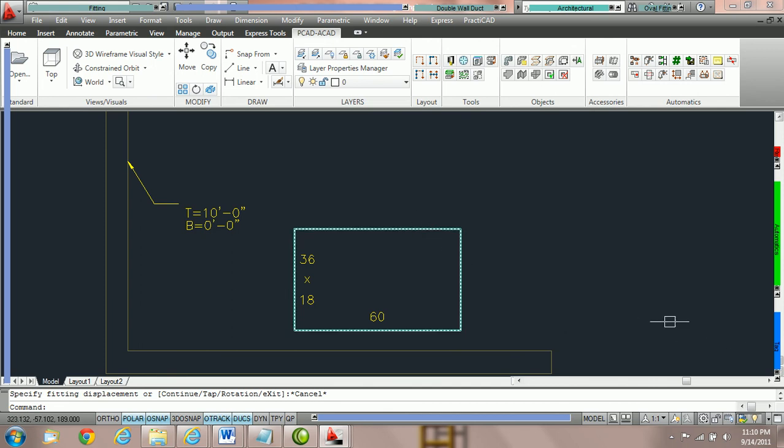However, this time if we go to do an elevation tag or just look in the elevation box, you can see that the bottom of duct is at 15 foot high. So we've done it correctly. So this is how to use your replace Z command in AutoCAD options.